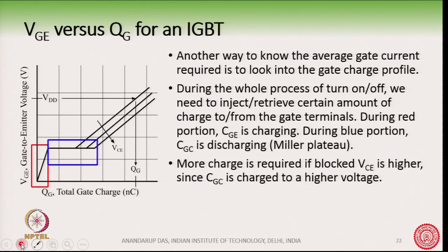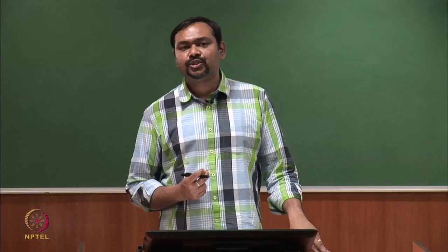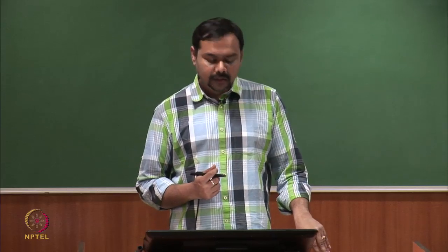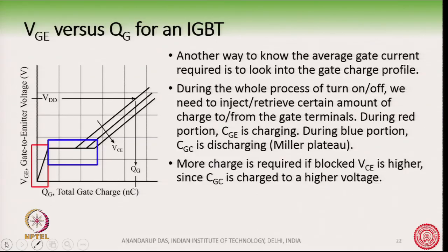Now, often people do not go in that fashion, often people design it in a slightly different way. Instead of exactly finding out what is the current required and what is the time required, the other way to know the average gate current is to look into the gate charge profile of the device.